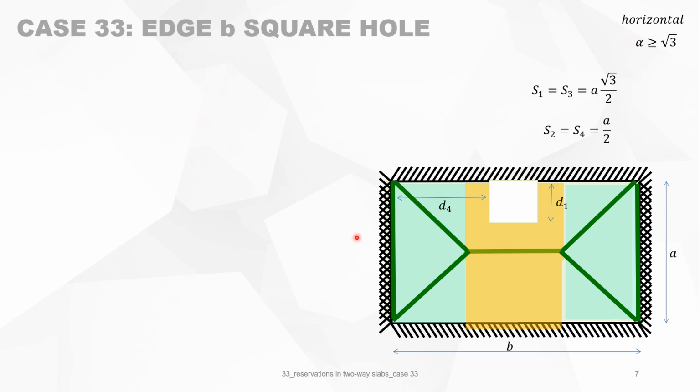We can now calculate the work done by the external forces. And this is equal to, when we look at the rectangular sections, A times B minus S1 minus S3, and we multiply by the mean deflection, which is delta over 2. We add to that the sections which are comprised of triangles. And this is A times S1 and A times S3. And the mean deflection is delta over 3.